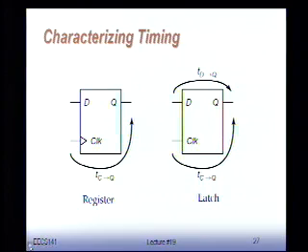Think about a register. What is the delay of a register? Well, remember, a register or a flip-flop changes only when you have a rising edge. Let's say positive, you have a rising edge on the clock, and then we will see a change at the output. We sample the input and we put it on the output, right? That's the idea of a register or a flip-flop. So what I really care about from a delay perspective is how long it takes between a rising edge on my clock and the input appearing at the output.